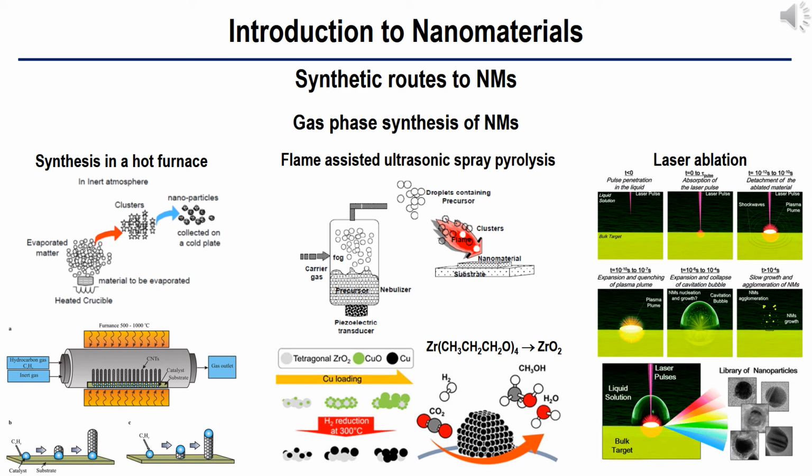The laser spark atomizer can be used to produce highly mesoporous thick films, and the porosity can be modified by the carrier gas flow rate. Zirconia and tin oxide nanoparticulate thick films were also synthesized successfully using this process with quite identical microstructure. Synthesis of other materials such as lithium manganate, silicon and carbon has also been carried out by this technique.